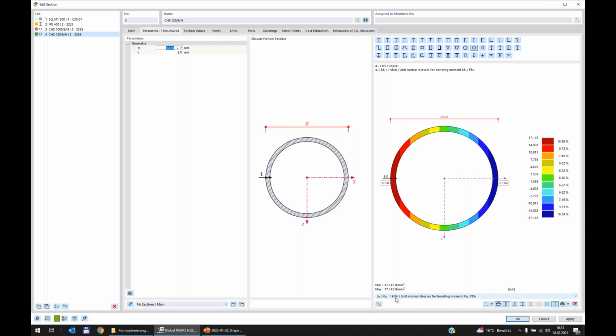So what is our condition on top? We have 0 bending moment, so I don't have to check bending stresses, because on top I have, let's say, no bending moment because I introduce only load. So we have a shear force.